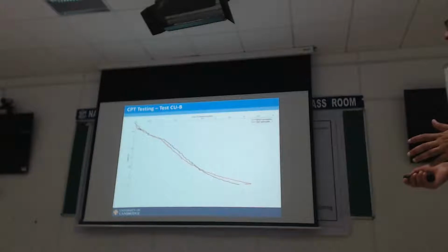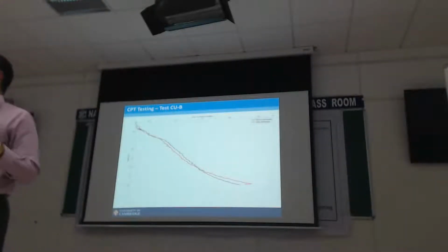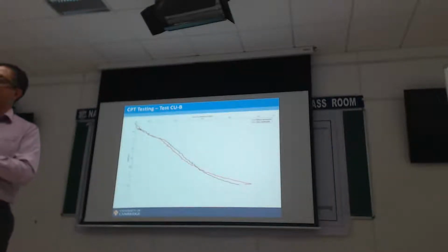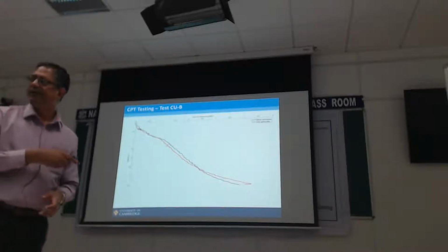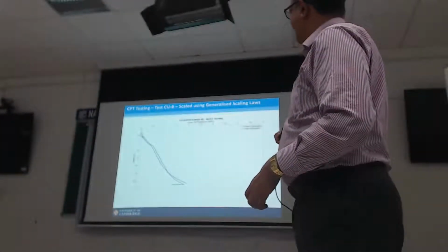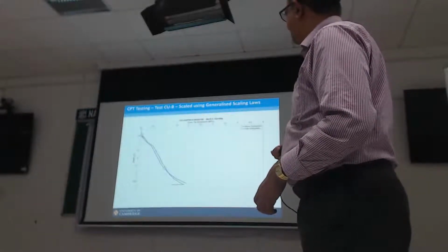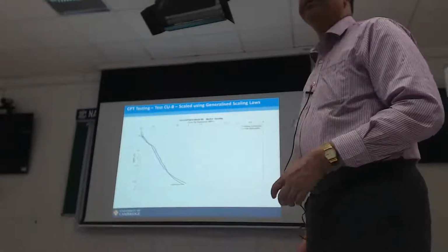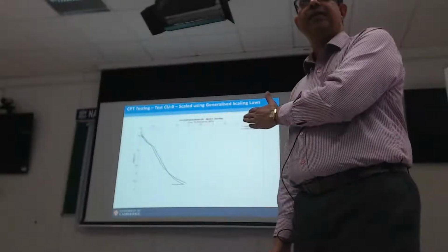Now, because cone tip resistance is a stress, according to what we are trying to do here, we need to use the scaling law for stress to scale this x-axis, right? So if you do that for this set of 80G and mu of half, my resistance drops at 2 meter depth to about 1 megapascal. So that's just once I use the scaling law to scale this. Okay.